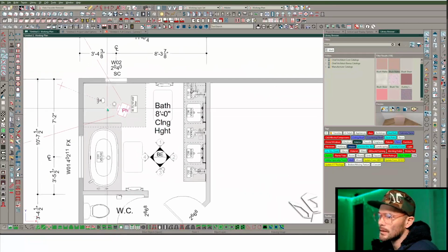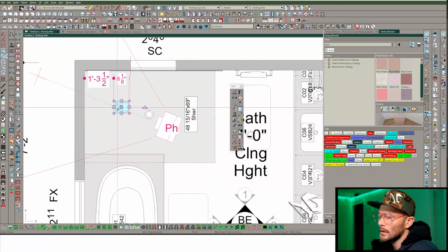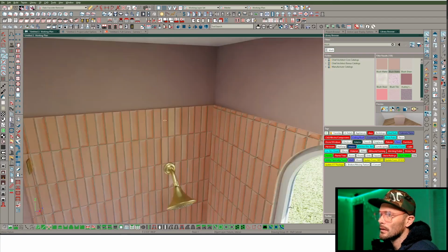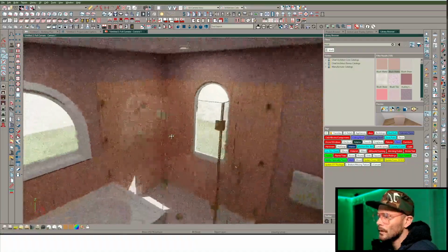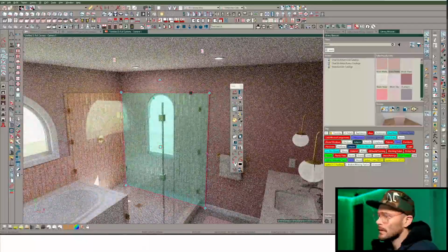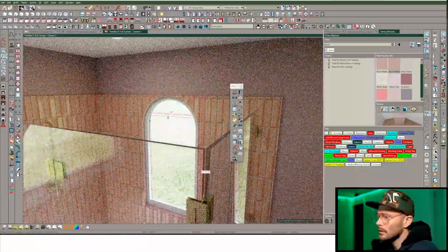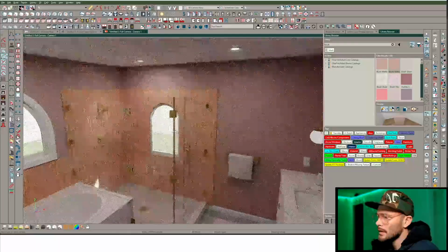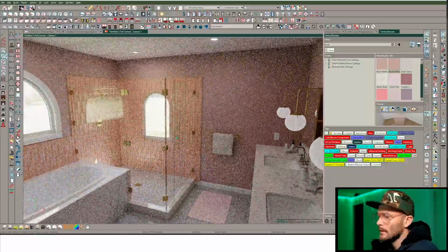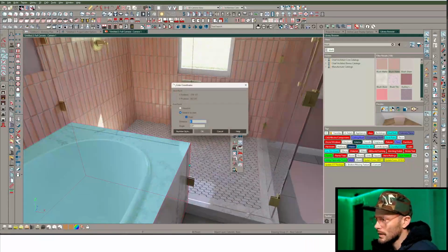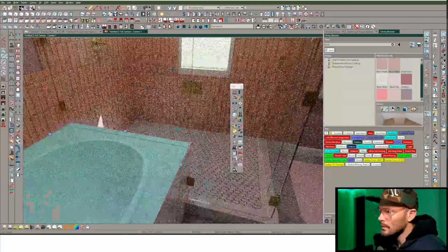Let's get into this plan view one more time and just pop this in here like that. There's that center I was looking for. Yeah, okay. I want this to be a little bit shorter. Might need to rebuild that. No, that rebuilt by itself. Cool. Looks like this is just doing a little bit of Z fighting, so we'll just move this 1/16, something like that.